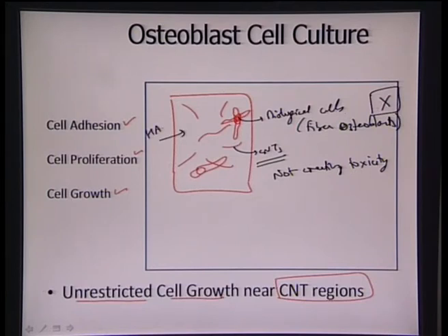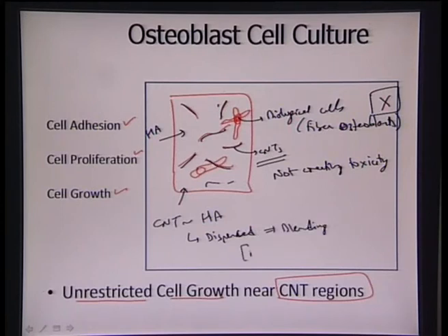So majorly we have the hydroxyapatite matrix with some CNTs here and there, scattered throughout the matrix, and it also appeared that CNTs are getting distributed even in the powder stage. It appears that they have some sort of a chemical affinity with the hydroxyapatite matrix itself. So they tend to disperse even just by blending, and it means that we are not doing any functionalization or surface treatment.